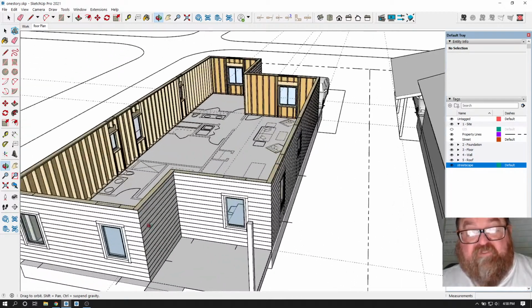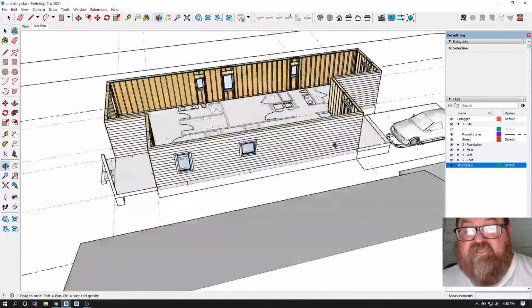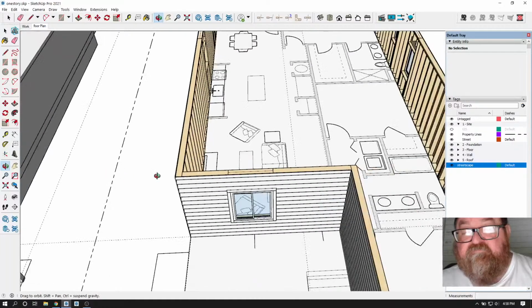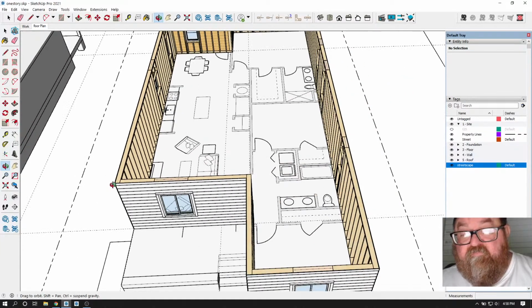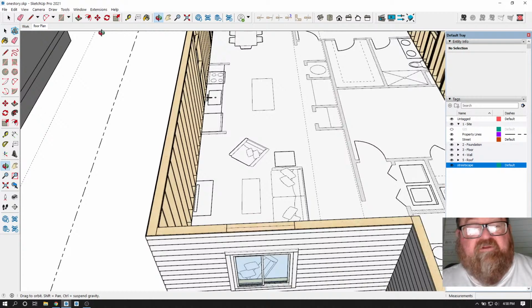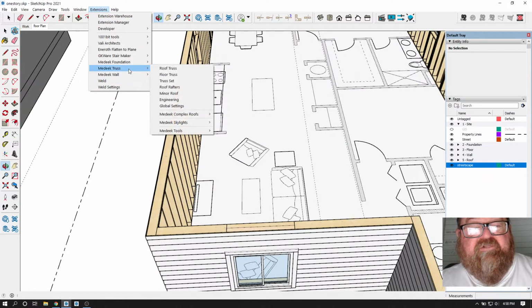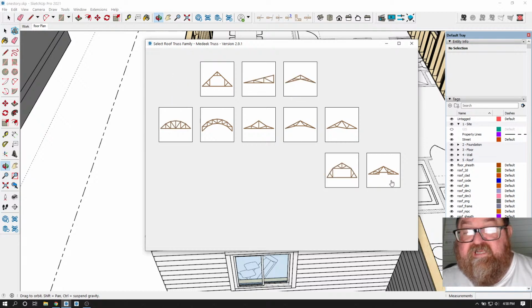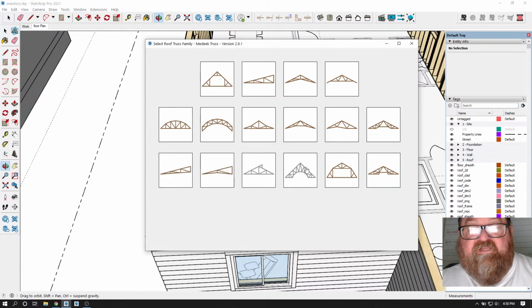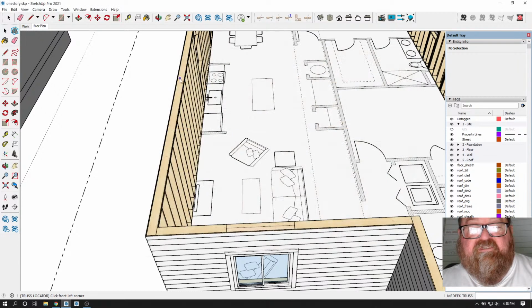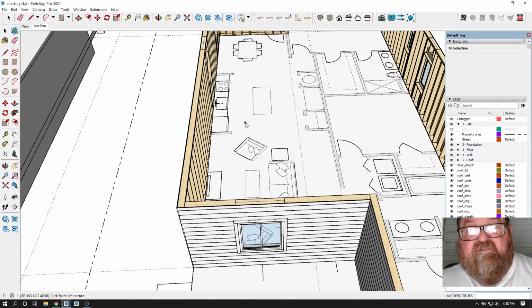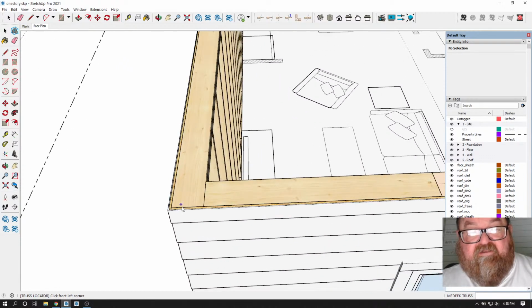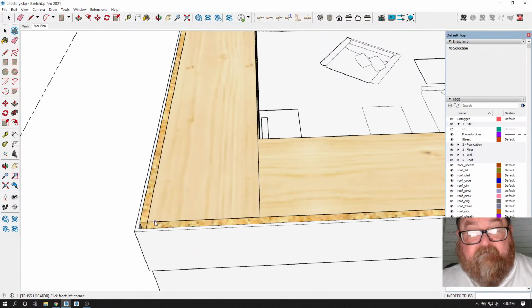We're going to start off trussing the whole thing just to see what it's going to look like. So yeah, if I start here, I'll be good. I'm going to go to extension, Medeek Truss, roof truss, and we're going to use a regular Fink. That's weird. I must be taxing my memory already by showing all these houses at once. I just happen to know where the Fink truss is located, but I've noticed I only have 16 gig loaded. I need to put the other 16 in.